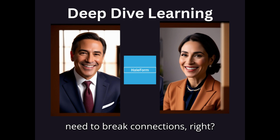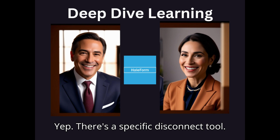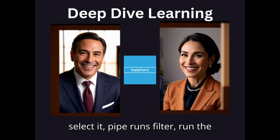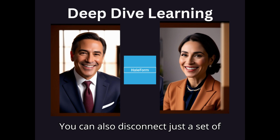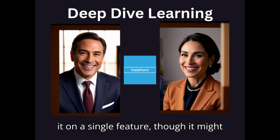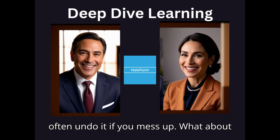Sometimes you need to break connections, right? Disconnect a run or just a few features. Yep. There's a specific disconnect tool. Find it under Tools, Utilities, Disconnect. To disconnect a whole run, select it, Pipe Runs filter, run the command, breaks all its connections, deletes mating parts at the boundaries. You can also disconnect just a set of features. Select them, Piping Features filter, run disconnect. You can even try it on a single feature, though it might not work directly on branches or end features that way. The tool usually gives you a log of what it did, and you can often undo it if you mess up.